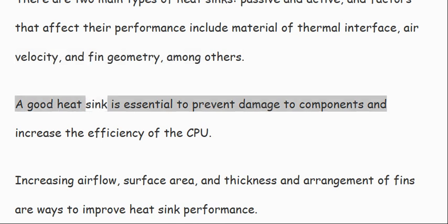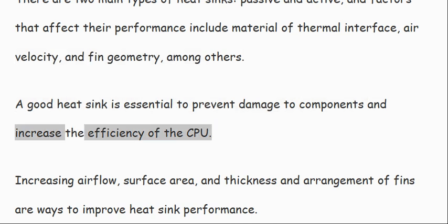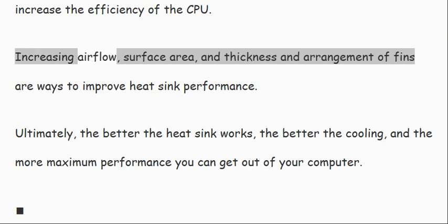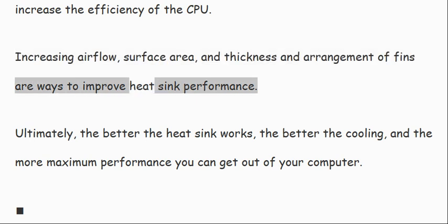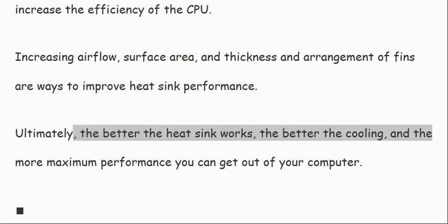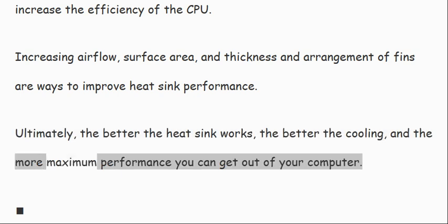A good heat sink is essential to prevent damage to components and increase the efficiency of the CPU. Increasing airflow, surface area, and thickness and arrangement of fins are ways to improve heat sink performance. Ultimately, the better the heat sink works, the better the cooling and the more maximum performance you can get out of your computer.